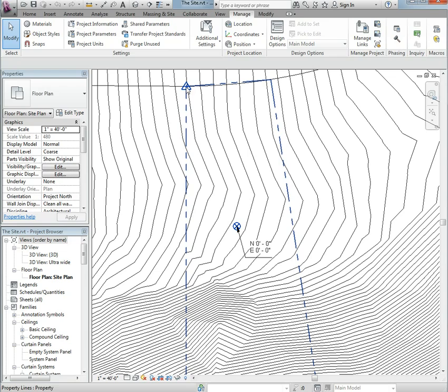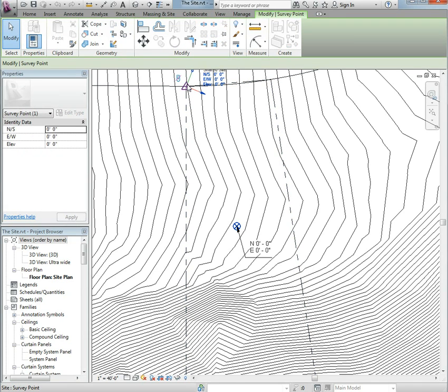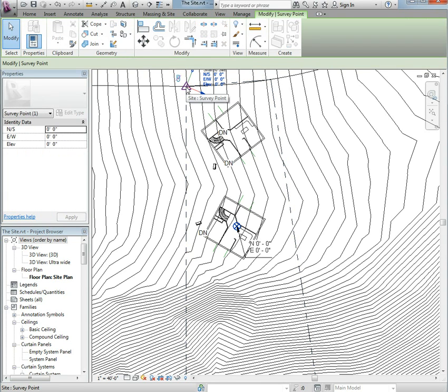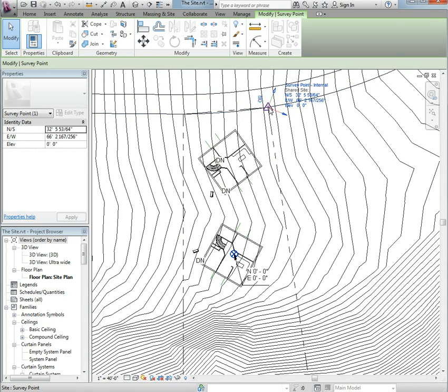Unclip it. I could unclip it, and I could move it over here. Actually, let me bring those links back up. I could move this marker over here in an ideal world, and I could just use this position as my new pin. All of my positions would update, and everything would be grand. But unfortunately, as it turns out, that actually doesn't work, and it's really a bug inside of Revit. And I'll talk about how we can get around this bug later.